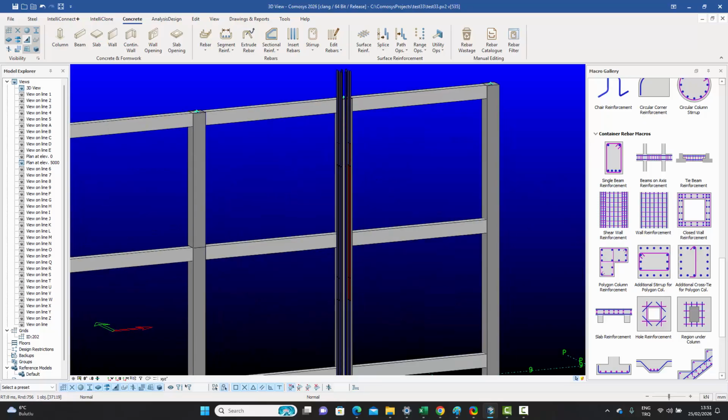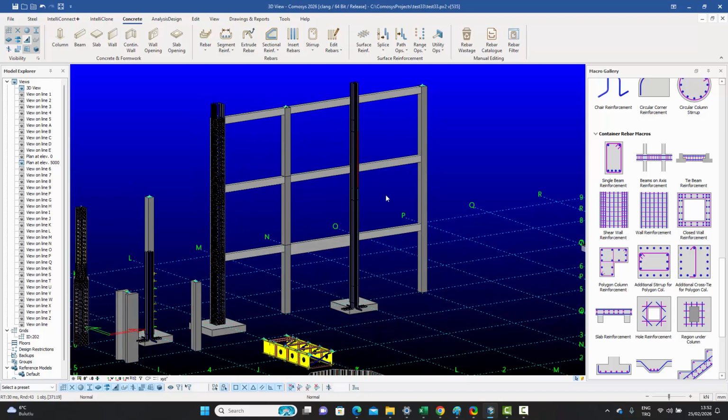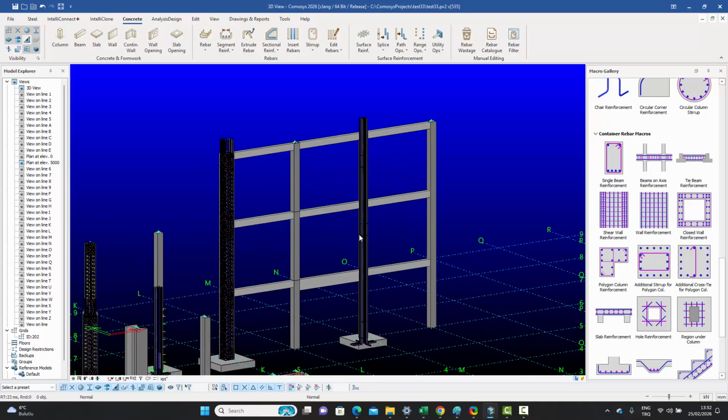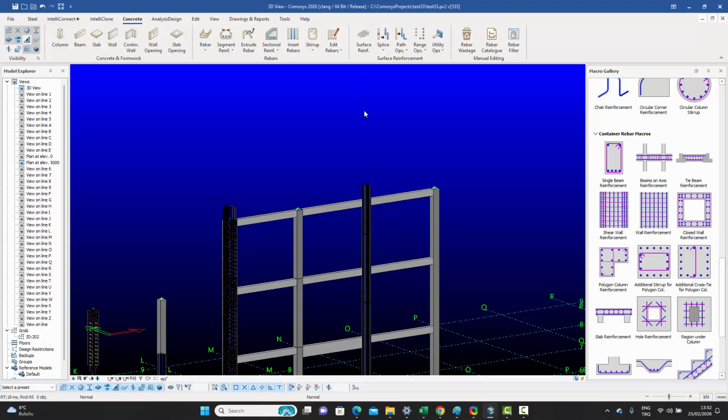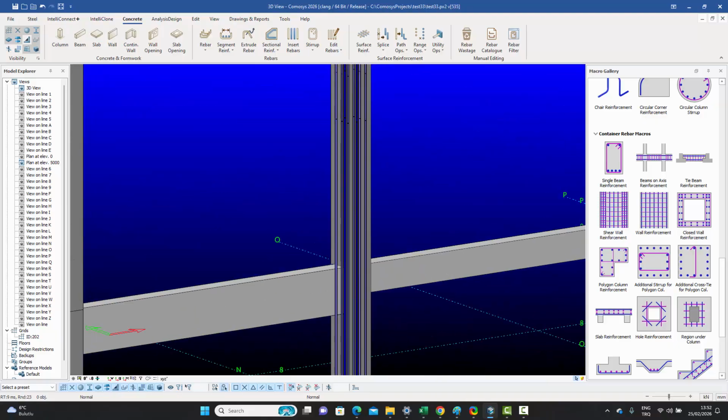I can change that. But you can notice that in a single go, I can define this if I've got a 4-story or a 5-story building in which the column, let's say the only requirement is that the column cross section needs to be this. Obviously, if it's a single column, then the cross section will be the same. So in those cases, you can define the reinforcement till that section is the same, and then you can easily apply the splices at whatever points. And for the continuation for the rest of the structure, you can apply the macros again and again. So it's a very convenient way of creating your own splices.